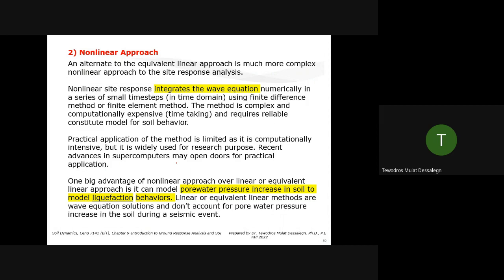It has its own advantages, but it also has its own limitations. It takes a lot of time. It's very time-consuming, computationally very expensive. But those approaches also model pore water pressure increase. If you do a dynamic analysis and predict pore water pressure increase at the same time, you can model phenomena like liquefaction. So that's the advantage. Plaxis and FLAC can model liquefaction. But the simulation takes a lot of time.